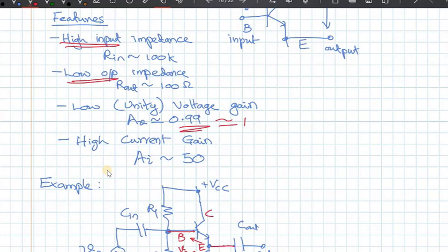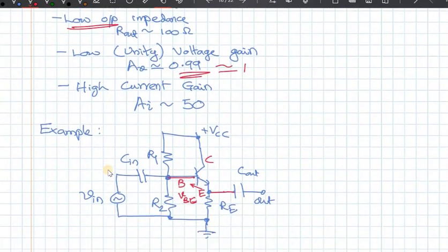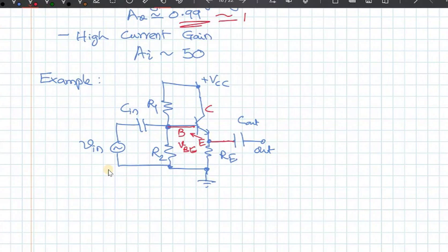So therefore, if you directly connect it to a high load, the microphone is not going to be able to deliver the required power. So you are not going to hear anything out of the speaker, which may have a low resistance. High load means low resistance, in the range of maybe 100 ohms, maybe 10 ohms, maybe even smaller, depending on what you have. So it cannot deliver that current.